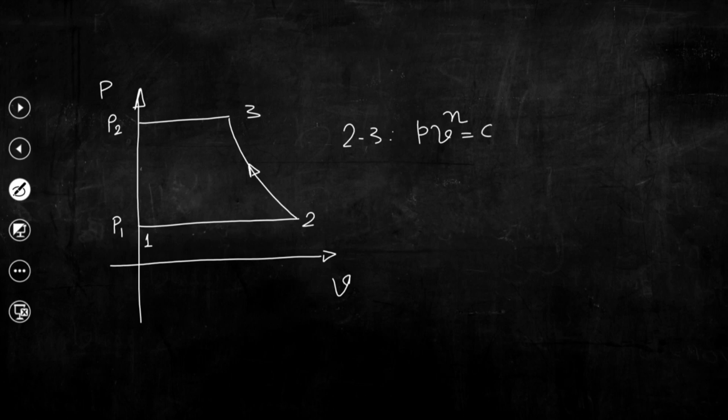Now, if we increase the pressure using a single stage, those problematic issues will be there: reduction in volumetric efficiency, reduction in COP, work input will be more, and the rise in temperature at the end of the compression process will be so high that it will have a detrimental effect on the mechanical components of the compressor.